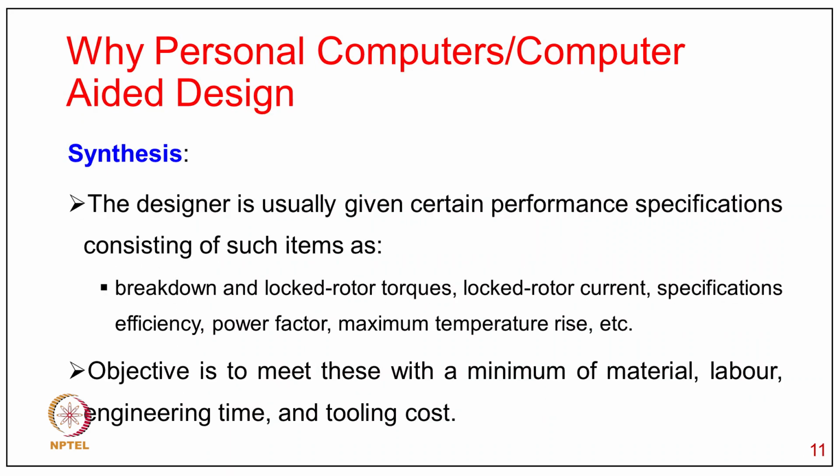Now the other approach of design, which we call the synthesis approach, for computer design of these single phase induction motors. The designer is usually given certain performance specifications consisting of such items as breakdown or locked rotor torque, locked rotor current, specifications like efficiency, power factor and maximum temperature rise, etc. And the objective is to meet these with a minimum of material, labor, engineering time and tooling cost.